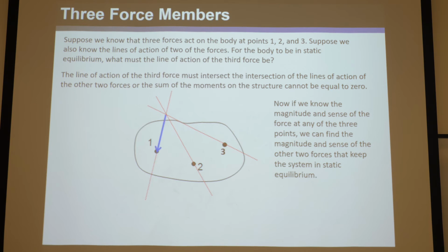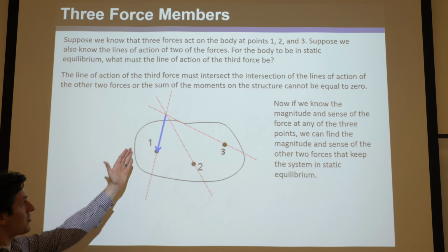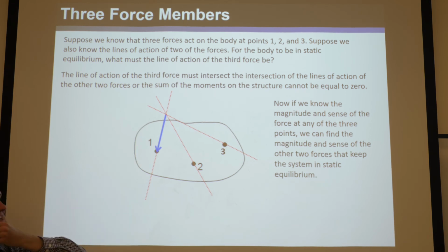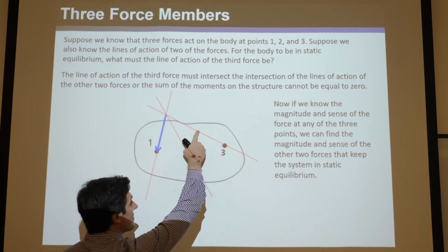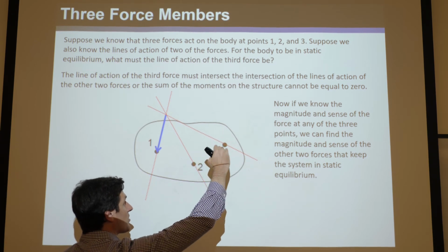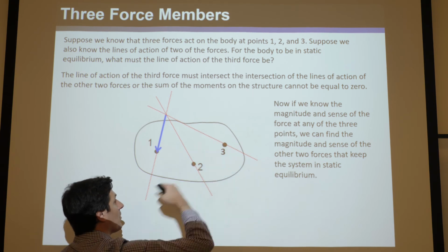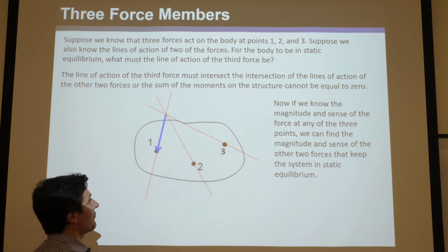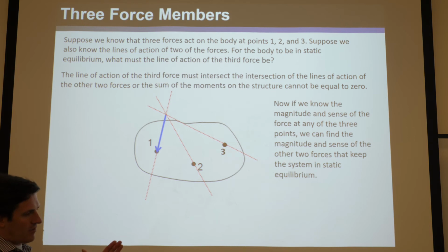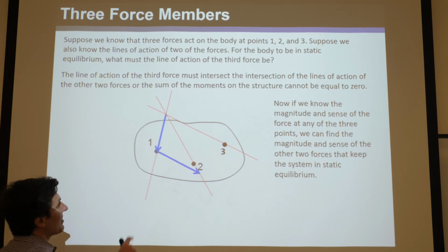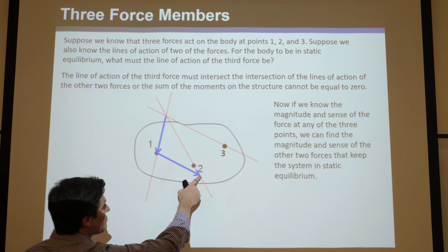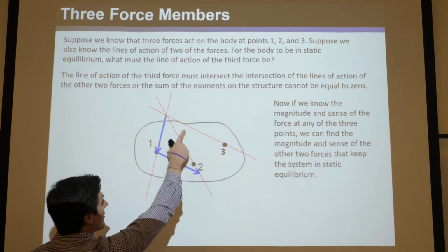So if we pull this back to where they all intersect, which we can do because remember it's still the same direction and magnitude, it doesn't really have a location in force land. And then we know that the force on this one has to lie, if you draw the force vector, in that direction. So it has to basically be parallel with it. And to make the force loop, it would have to be this length until it hit this red line. So see how this is parallel to that?